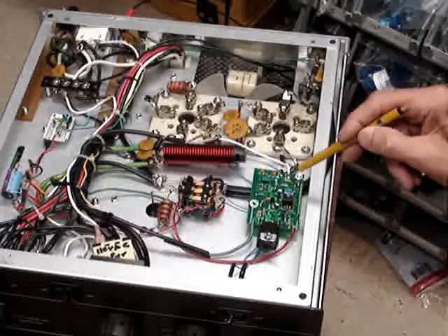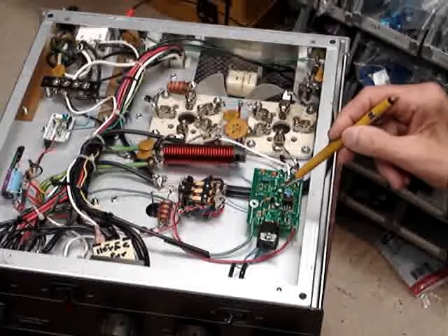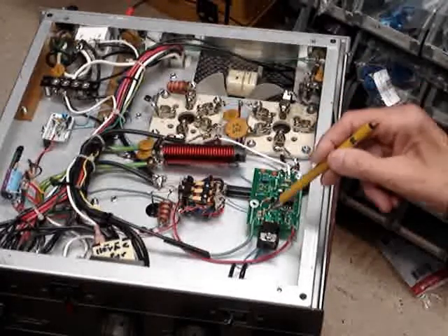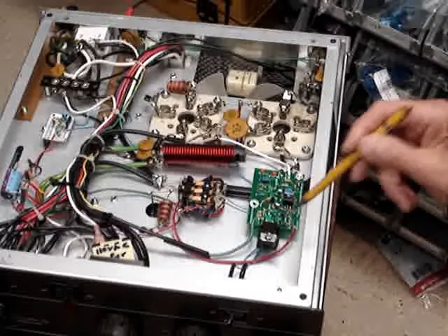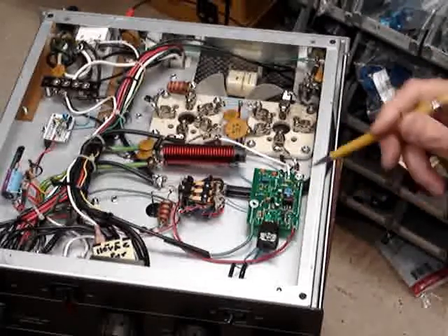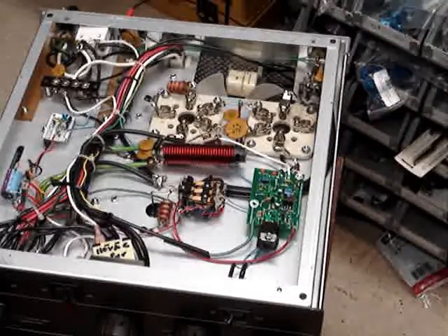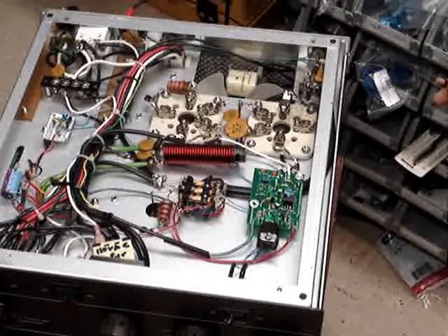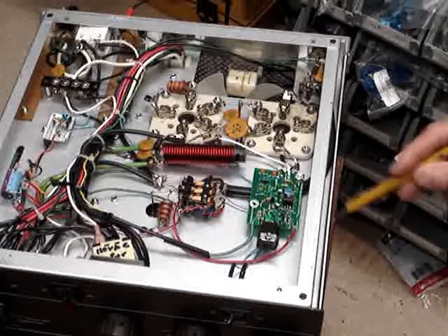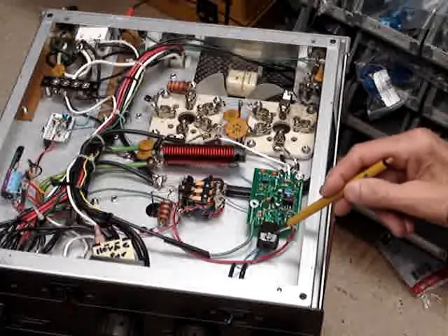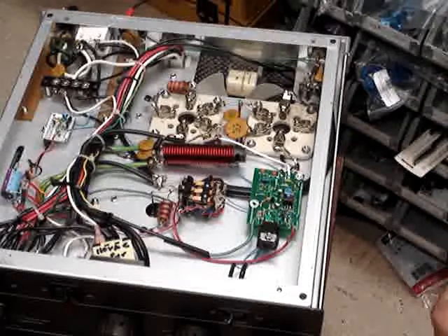It's not a real big problem. And the lower the bias voltage, typically the lower the dissipation in this pass transistor, because most amps, and I'll just have to typify that, most typically don't draw over an amp or a little over an amp of current. So the bias voltage tends to be more dissipation the higher the bias voltage you require.